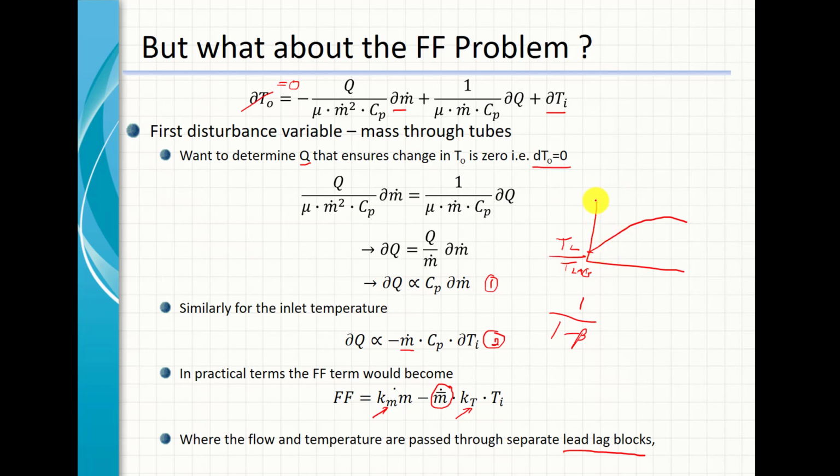If your lead time constant is larger than your lag, then you're going to have a higher response like that. So this is how you would solve the tuning for a fired heater where you cater for 2 feedforward effects and for turn down and gain scheduling. So it solves 3 things in one, and it can all be done on a standard or modern DCS system using standard calculation blocks.